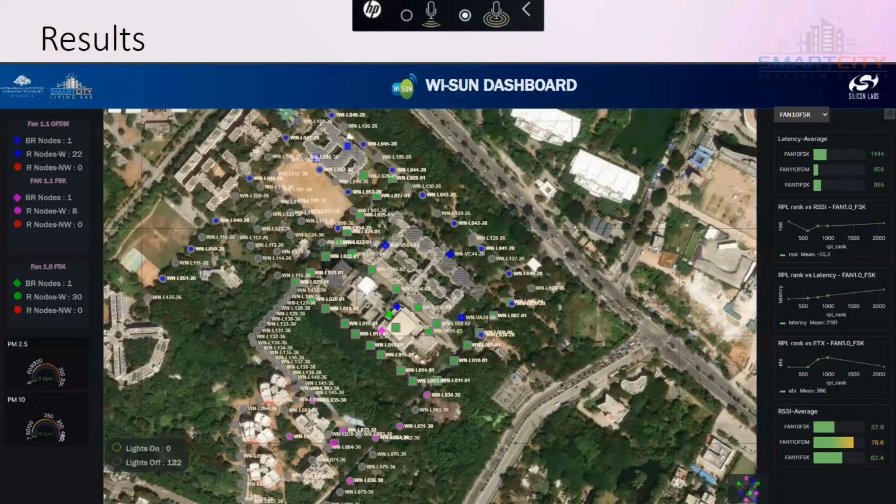All of these points that are being shown in blue and green are the street lights in IIIT, and they are all connected through Wi-Fi. Sitting at a dashboard, I can then switch on, switch off a bunch of them. I can automate it based on weather conditions or timing. In the future, we want to automate it based on whether people are walking there, like using a PIR sensor to sense whether a particular street is being used or not.